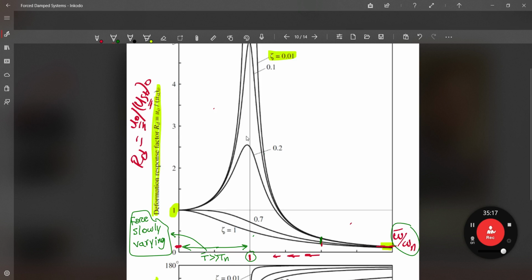You're going to find that here, here, here, there is almost no difference between the types of damping that we have. It doesn't matter, because here really it doesn't matter. Damping does not matter in this case if we have omega bar over omega n very small. Okay, why? Because we are going to have U node in this case, which is almost equal to U static node. The dynamic amplitude would equal the static amplitude, the maximum amplitude, equal to P node over K.